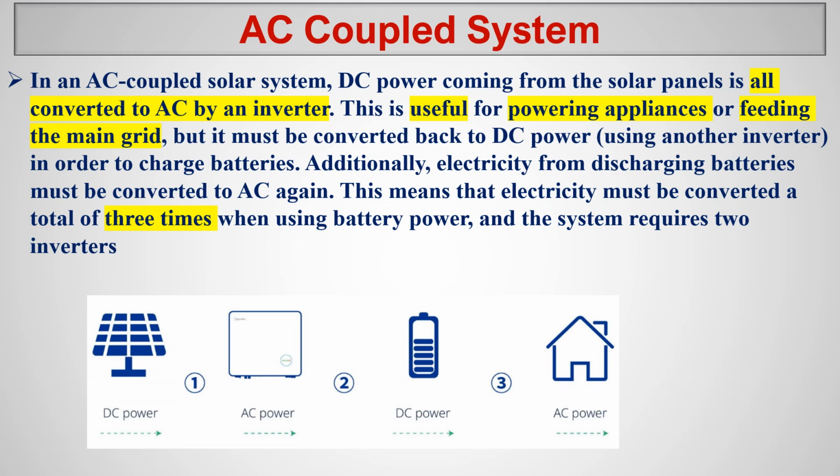Okay, then another reason. Let's say you are installing a huge 30 kilowatt system in your house, but your house is consuming only, let's say, 1 kilowatt, 2 kilowatts, a very simple house. Your consumption is very low. Now your target is to sell the power to the grid and get the money. Profit making is your target. Then why would we want to store in the battery and then convert again into AC? So in this case AC coupling is best, because you directly convert whatever solar power is generated from DC to AC and supply it to the grid. So directly the transaction is very easy.